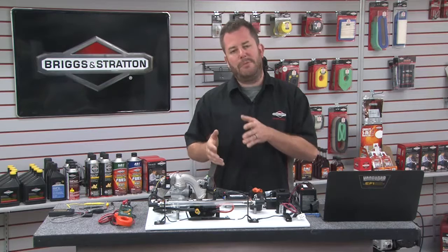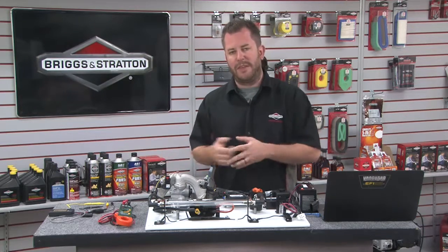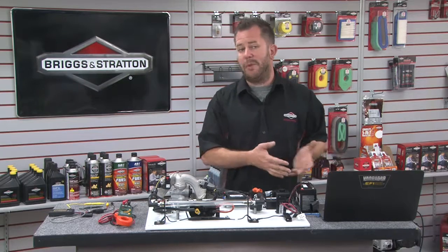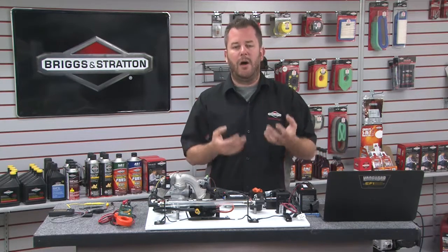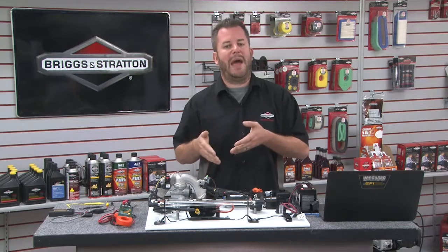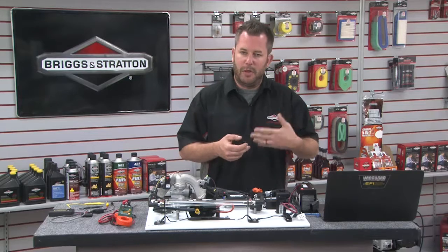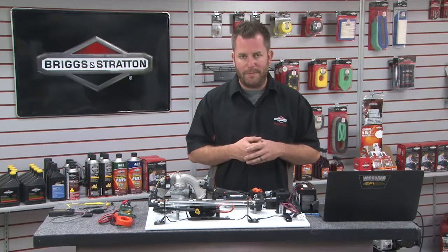So we usually have to remove a little bit of ignition timing advance to keep the engine safe. So it's all about trying to keep the engine optimal to a sweet spot of operation, of course, for the given conditions. Now, the inverse of that, when we go colder, now there's more oxygen content available. We can add a little bit more fuel to match that, and then sometimes we can ramp in a little bit more ignition timing advance for a little more of a power yield there as well.